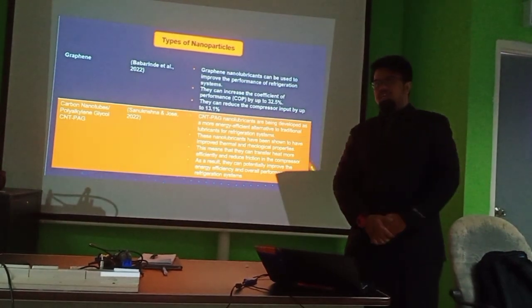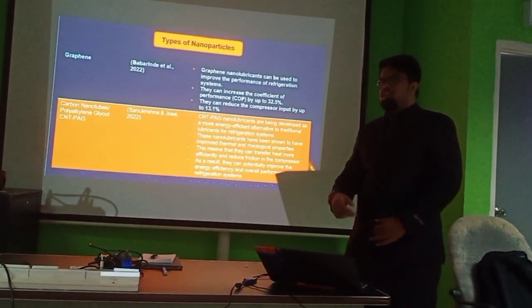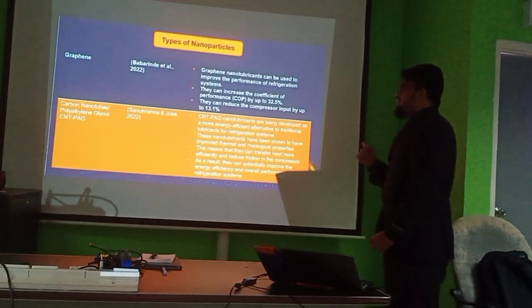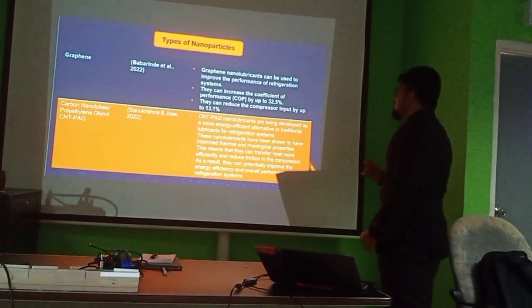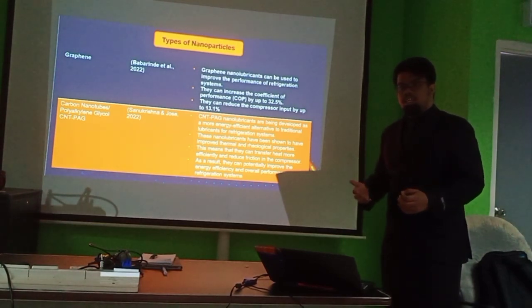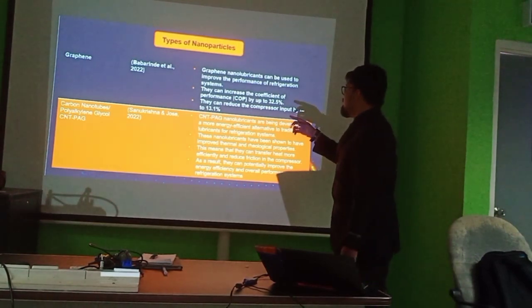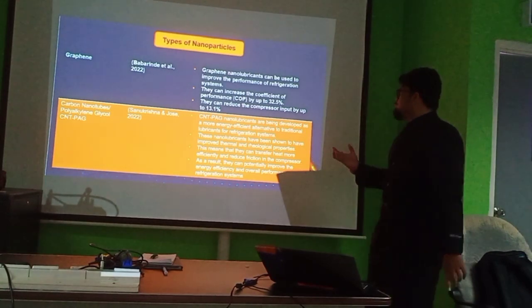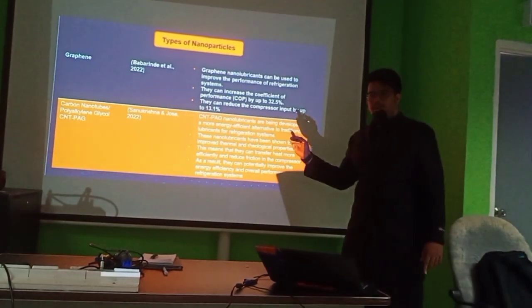All the system that include in the VCR have compressor that contribute more energy. So by adding the graphene, it can reduce the compressor input by 13.1%.